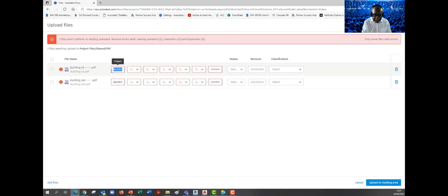So it's CL 00201. And it goes blue to say it conforms. Then we go to the originator, which is me, and system. Level location, we'll say it's on level 0. Type, it is a drawing. Role, we'll say it's architectural, and then you give it a number.